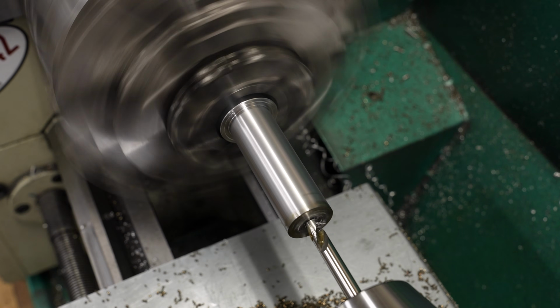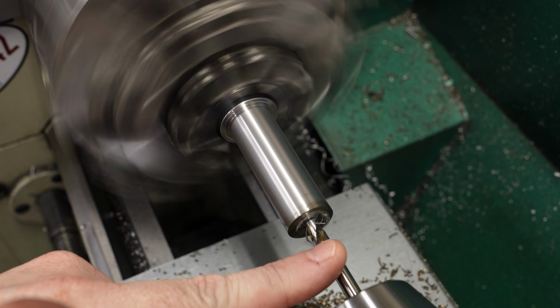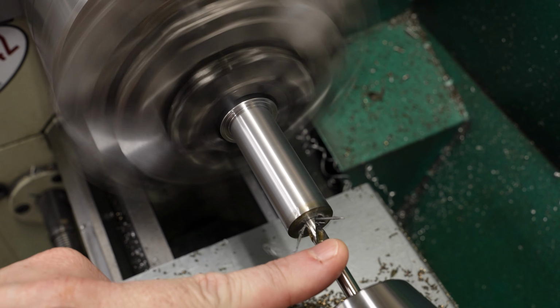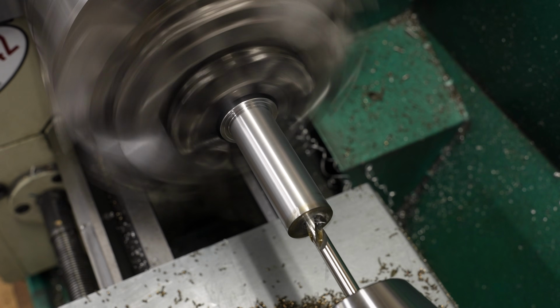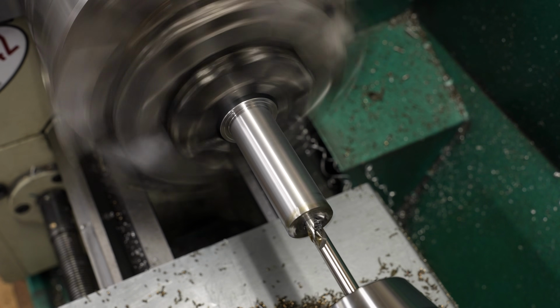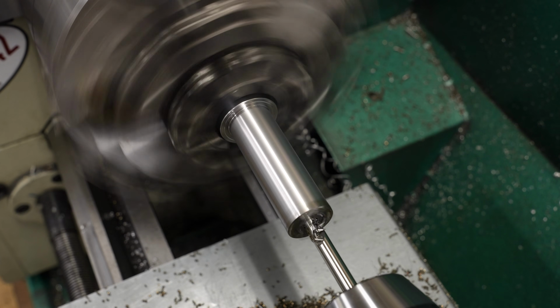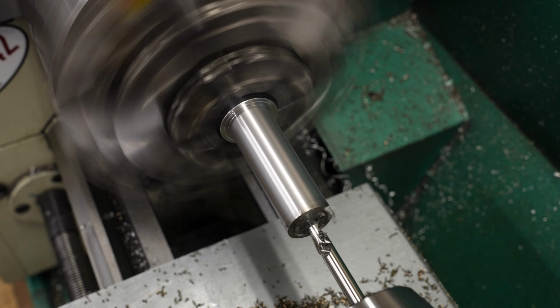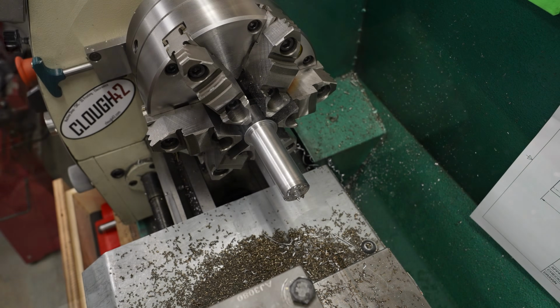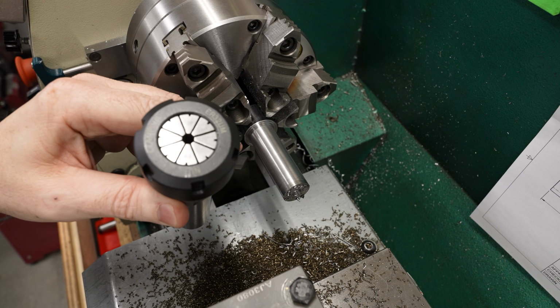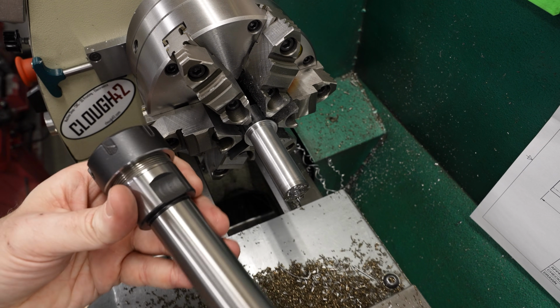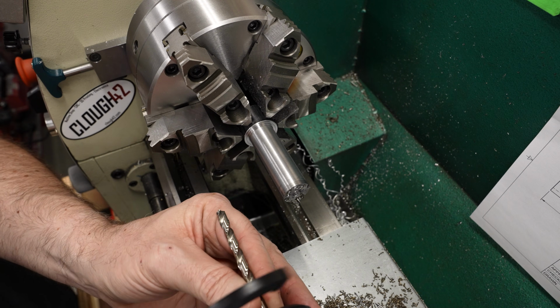I'm starting here with a 120-degree spotting drill, and I'm feeling the drill body just to see if there's any oscillation, see if it's moving because it started off center. And this feels pretty good, so I will go ahead and push it in deeper than I would normally push in a spotting drill, because I'm going to switch over to a jobber length drill held in a collet holder in the tool post. And then we'll go ahead and push this hole all the way through.